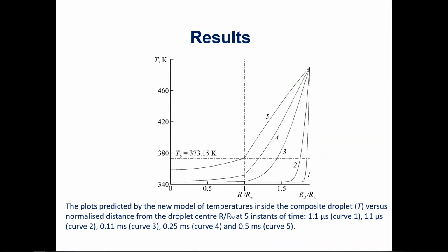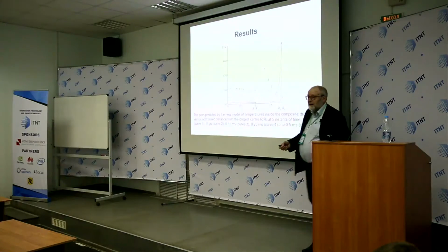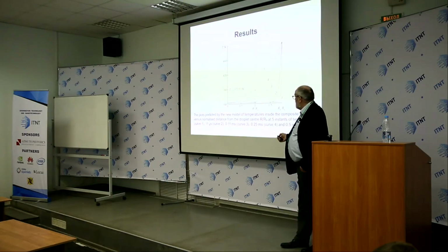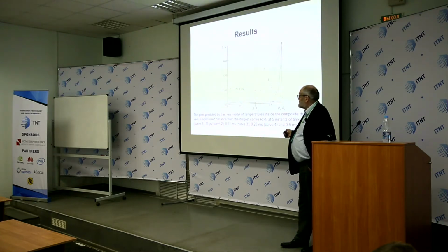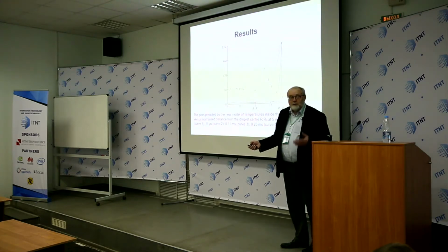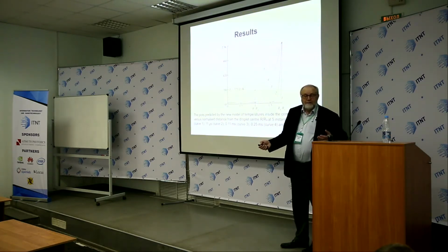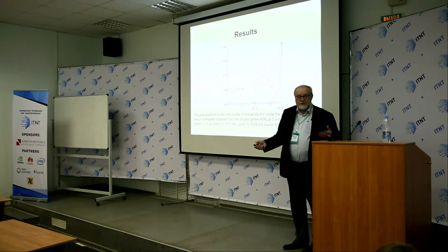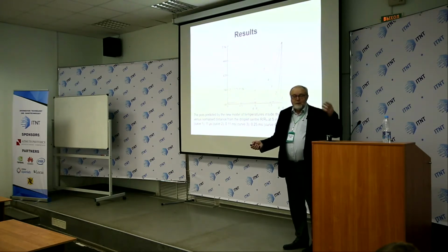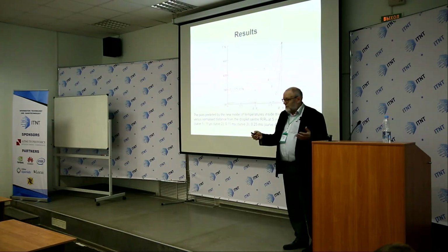And this leads to the gradual increase of temperature at the interface between the water and the fuel. And eventually, at some stage, that is time instant 5, the temperature at the interface between water and fuel reaches the water boiling point. And we assume that at this stage we have microexplosion. Strictly speaking, it will be puffing, which leads to microexplosions.